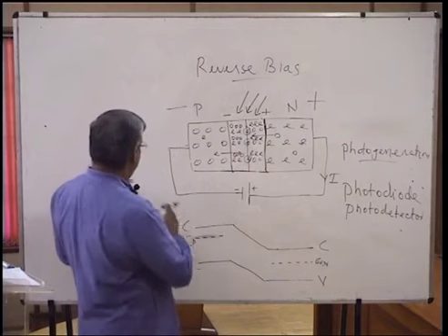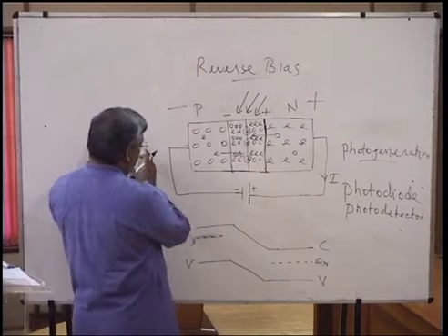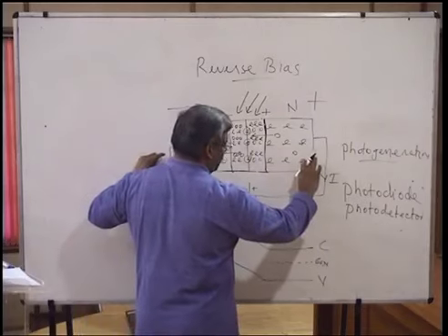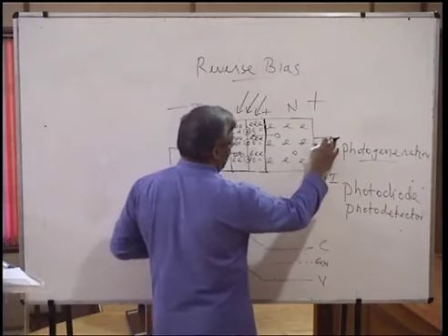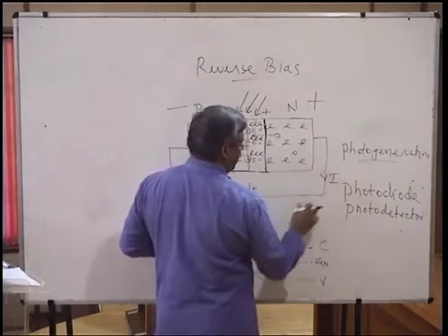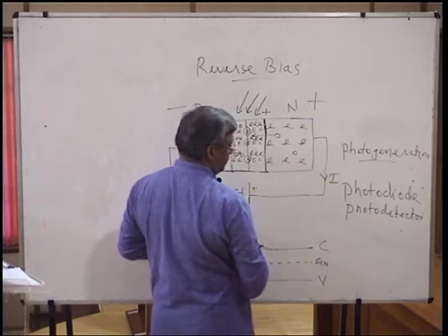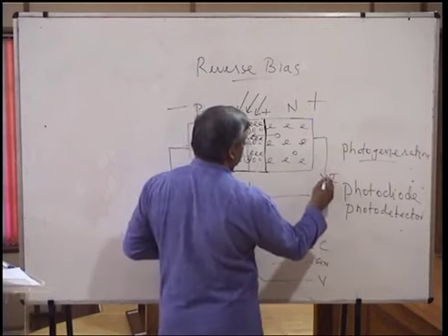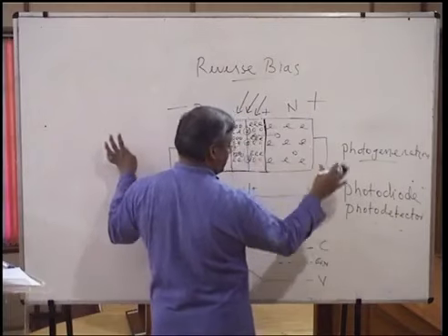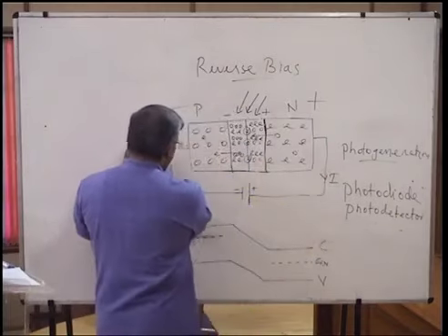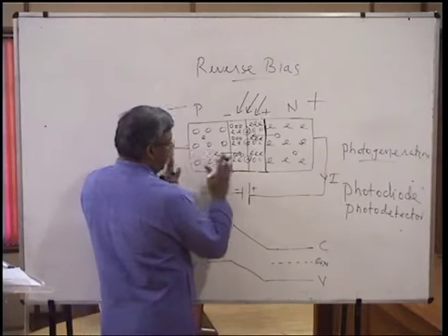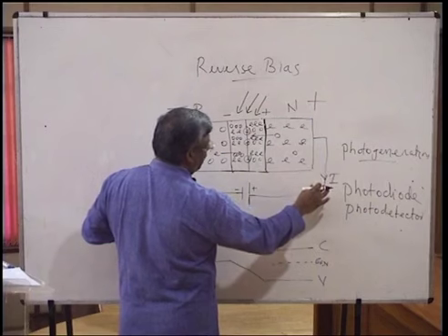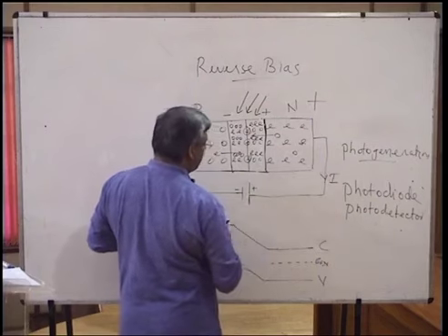So therefore, if you can send a signal by transforming the signal into a photon and carry that photon through an optical fiber, and at the other end, you can detect the photon using a photodiode or a photodetector, measure intensity, and recreate the signal, then the communication cycle is complete. So a transmitter with LED and a channel using optical fiber. On the other side, you have a photodiode as a detector.